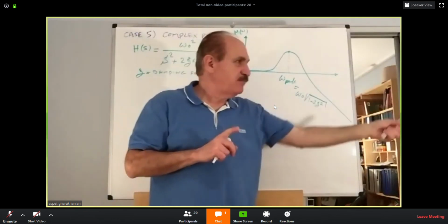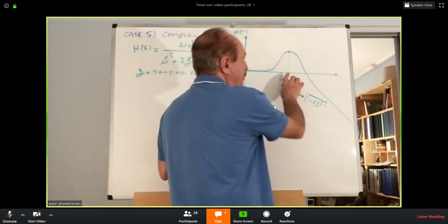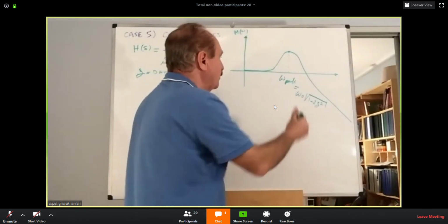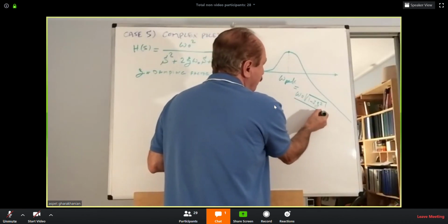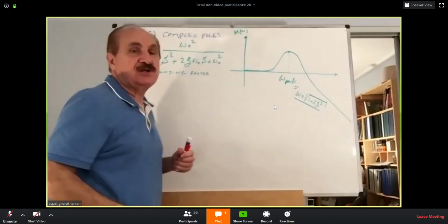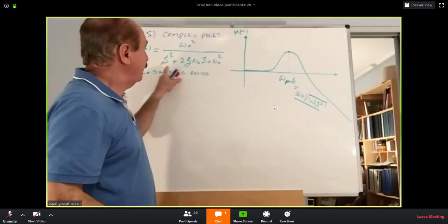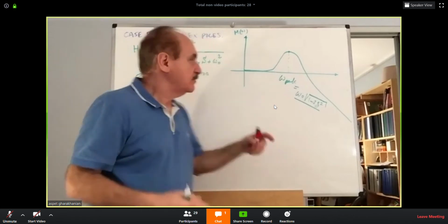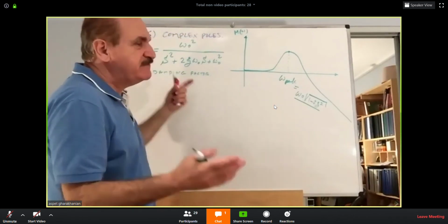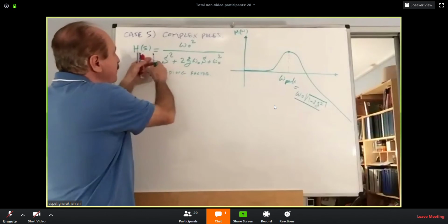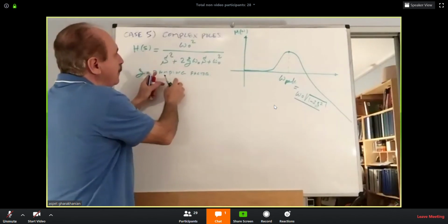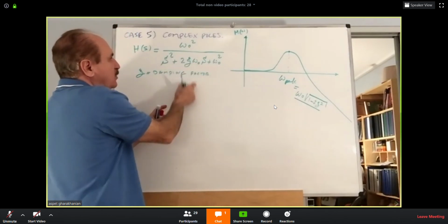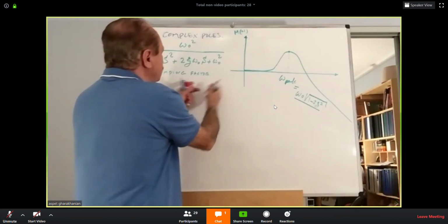If you pass that point, past the resonant frequency, it will start decreasing. It will go towards the negative dB. This can be computed from the transfer function itself. Usually the transfer function comes in terms of numbers, but you have to normalize them into that form. It's pretty easy. Simply factor out the coefficient, then match what stays here against omega O squared, and match that one again to zeta omega O. Then you can work it out.